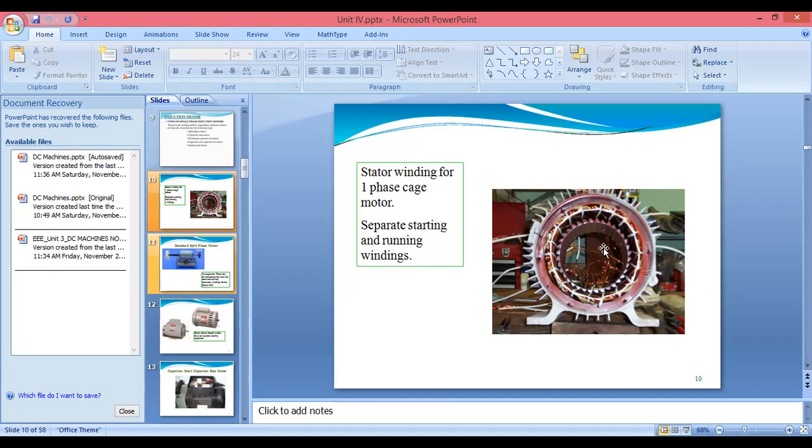So what are we saying about the rotor? The rotor is the rotating part of the induction motor, which is placed concentrically at the center of the stator winding. The rotor we can make using steel laminations, which have slots for the rotor conductors. The slots are not exactly parallel to the axis. This arrangement will reduce the noise and will avoid stalling of the motor.